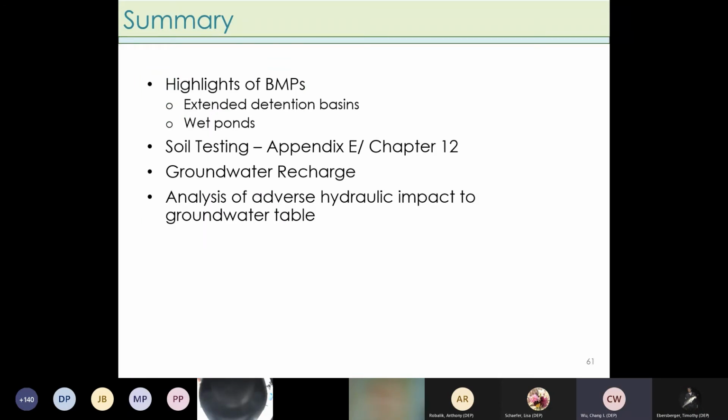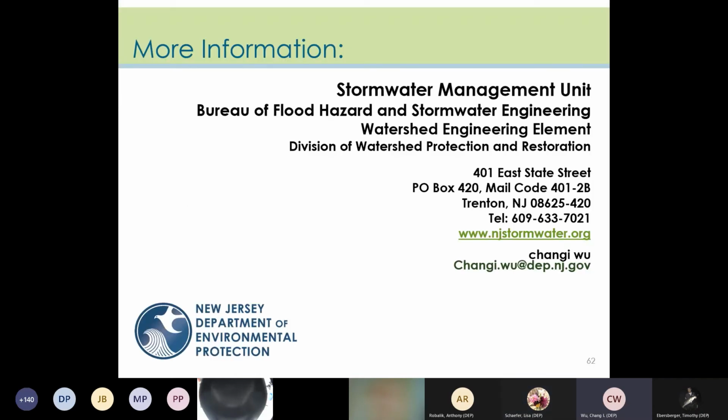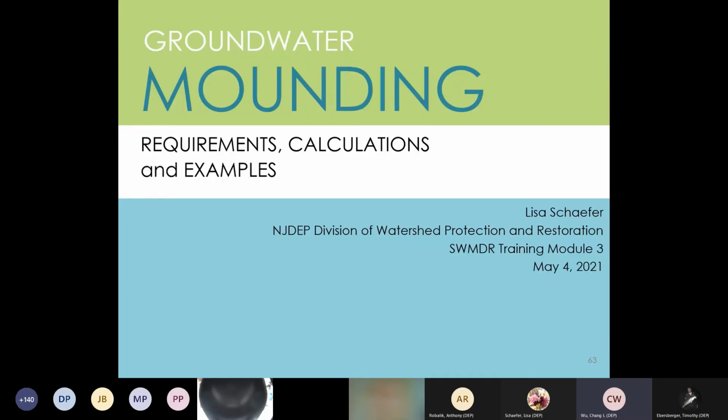So we talked about the extended detention basin, wet pond, and have some examples for the infiltration calculation. And then the soil testing, which used to be Appendix E, now it's Chapter 12. Groundwater recharge, and the next one will be the groundwater mounding analysis that will be addressed by Lisa. So here is my information. If you have further questions, you can contact me. So next will be Lisa for groundwater mounding analysis.